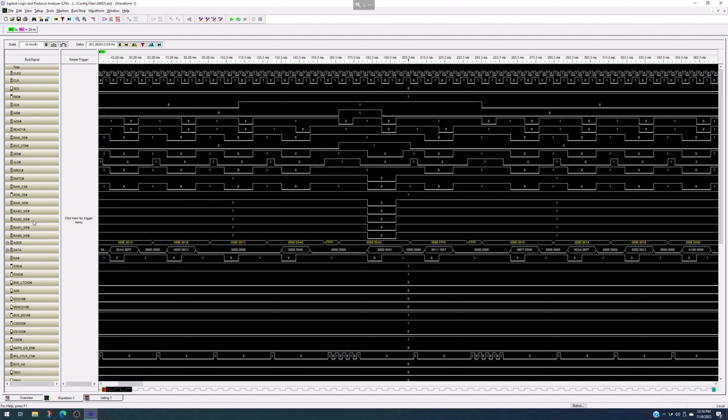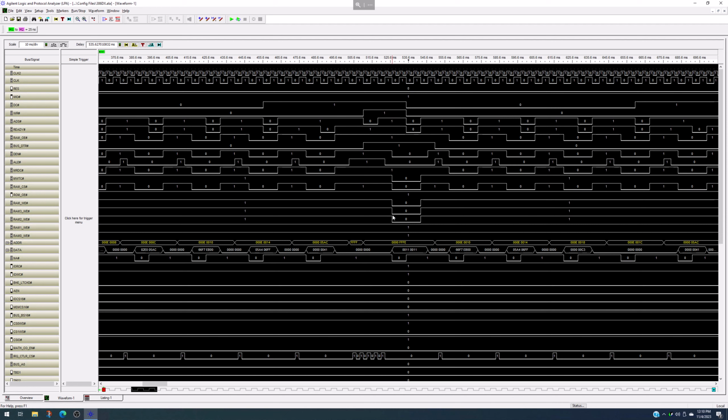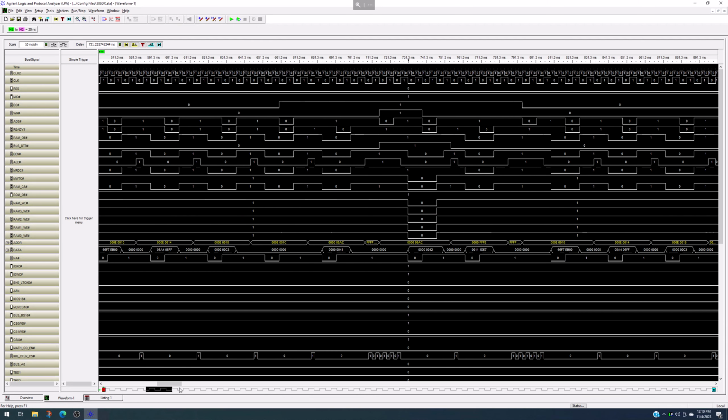Here's all my ROM writes. So there's a general ROM write signal, and then I've got RAM write, and for each of my RAM chips I can tell, and in a previous video I pointed that out, like here it's writing to all 4 RAM chips at once. If I scroll to the right, here it's only writing to 2 of the RAM chips. So it only wrote a word: it wrote 16 bits of data to RAM instead of 32 bits. And that would have been based on whatever my code was telling it to do. I formatted the address to be yellow. You can do all kinds of formatting in here that I'm learning how to do. But this is letting me now kind of interrogate, what am I seeing?